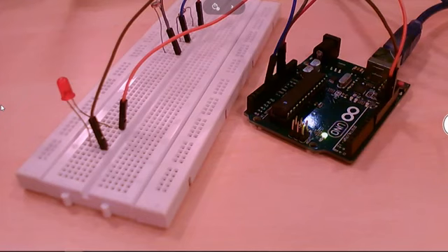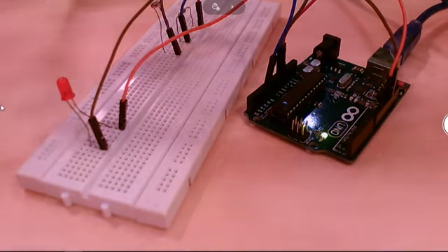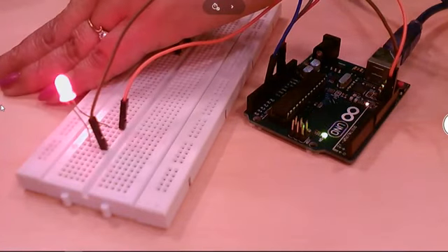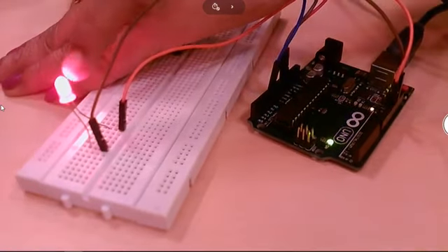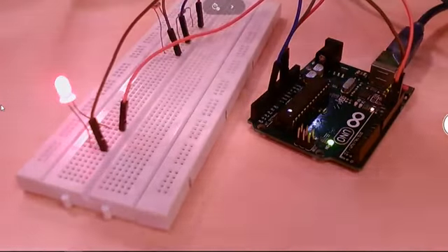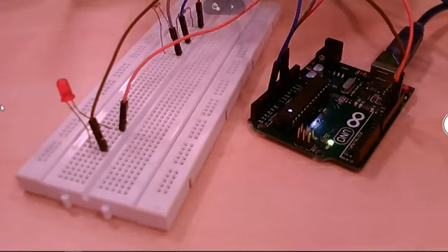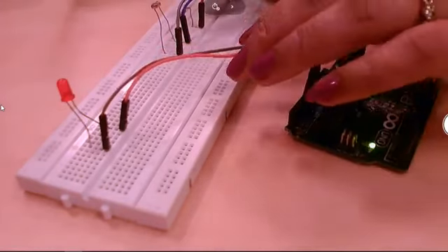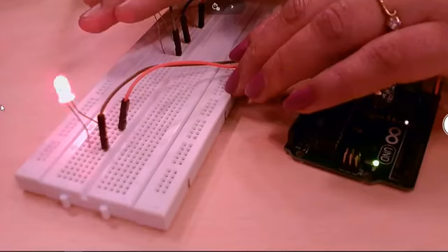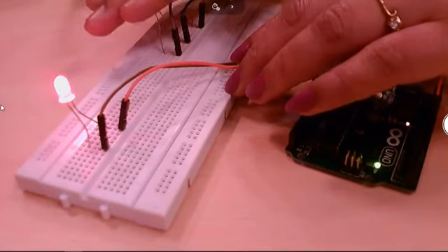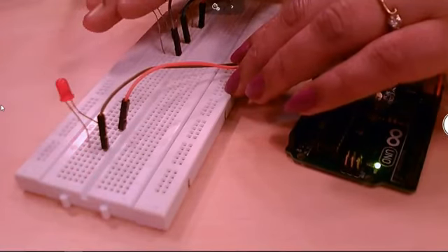So let's have a look at the output once again. I put darkness on that LDR by putting a hand on the LDR. The moment the value has gone high, above 1021, the LED is on. You can see that the LED is on here. I remove the hand from the LDR, more light is falling on it. Again I put the hand here. So changing the intensity of light falling on the LDR is actuating your LED. Isn't it interesting?